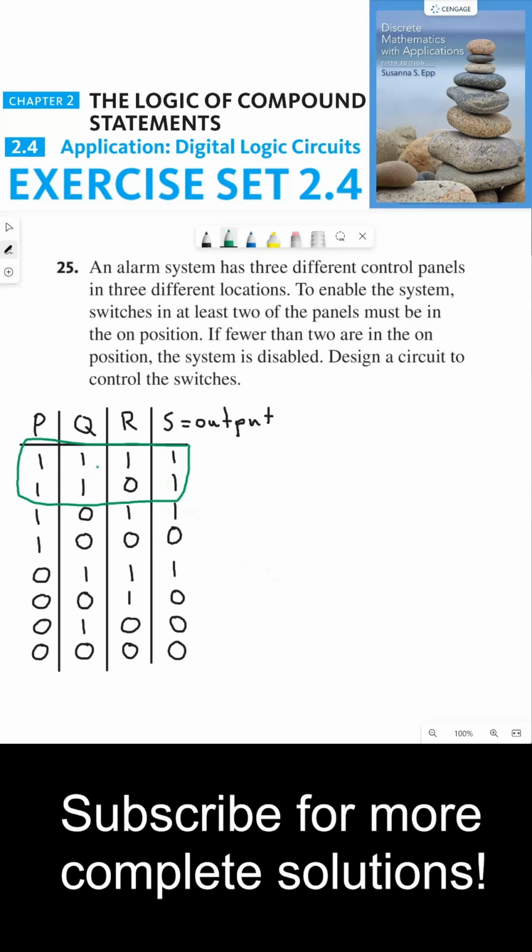Now let's consider the first 2 rows at the same time for a second. If you notice, if P and Q are both 1, then it doesn't matter what R is, the output of S will be 1. So we can say that S is 1 precisely when P and Q is true, regardless of what R is. So under these assumptions, where P is true and Q is true, S is also going to be true, or have an output signal of 1.